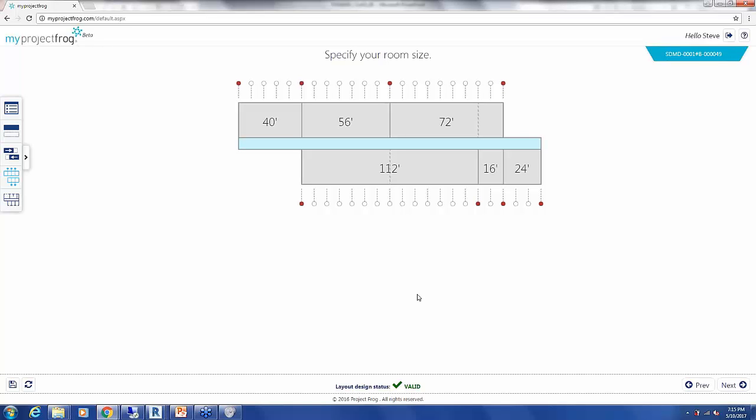And so once you get a valid statement here, we can start to add rooms and separators, and really I should call these collector lines. So obviously there are going to be shear walls starting to be placed in some of these walls, depending upon if shear needs to be placed inside of these lines of structure. So here's my wonderful frog building. As it validates, I'll go to my next step. It's grayed out until it actually gives you a valid building.